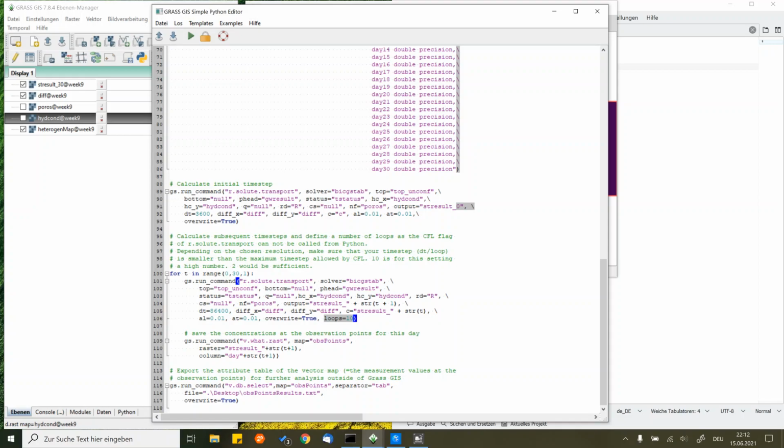You can increase the number even further. It doesn't change much besides increasing your computational costs. But with 10, it was still very, very quick and very performant on my PC. But the least number you are required to put here is 2 to fulfill the CFL criterion.